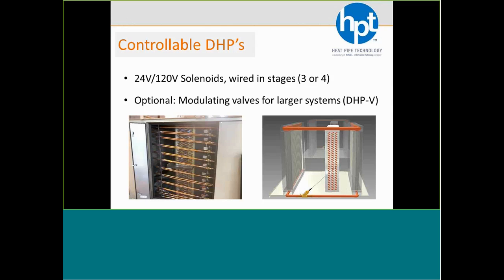The downside here is that you do lose a little bit of performance, because pulling many circuits into common headers is going to lose some performance for you. So we only go this route. We like to capitalize on the performance of the wraparound as much as possible. So we're only going to go this route when it certainly calls for it.